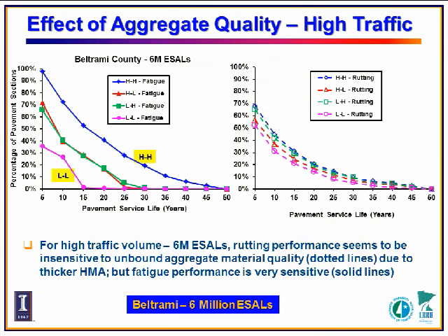What's the criteria for rutting? I didn't quite get that. The criteria for rutting is based on transfer functions based on the compressive vertical stress on top of the subgrade, and so the rutting criteria is only in the subgrade. Yes. Okay, so you haven't considered that the subbase may actually rut. Yes, that's another thing I'm going to talk about later. So right now we just use MnPave analysis. So fatigue is based on the tensile strain at the bottom of the HMA, and rutting is based on the vertical strain on top of the subgrade. Just like the Asphalt Institute, MnPave only considers rutting coming from the subgrade.